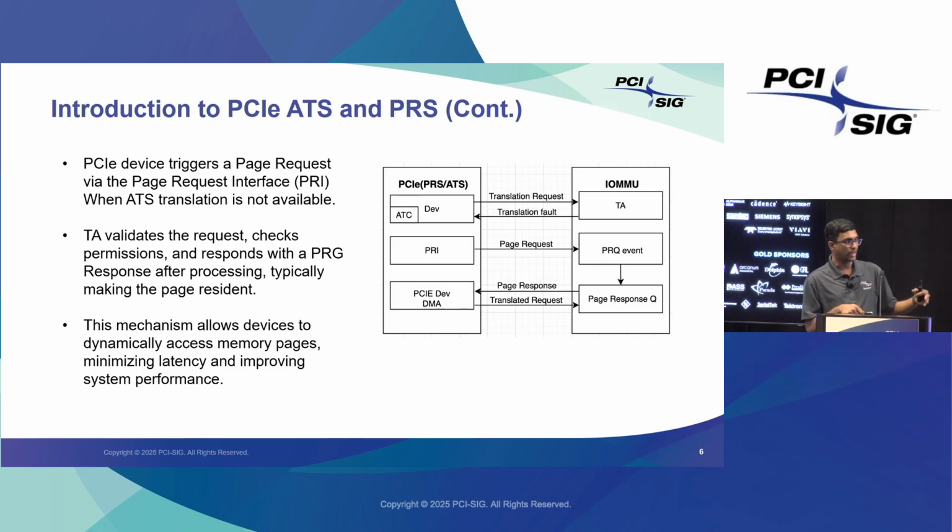We are going to the next request, and we are making our DMA without stopping our internal FSM. We are continuing that work, and we are just waiting for the page response. If we got the page response, then we are continuing the previous transaction, the previous DMA instruction. Okay, so this is PRI capability.